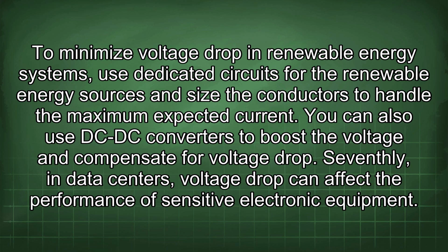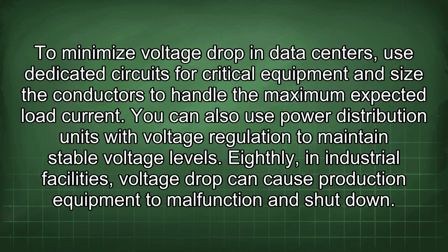Seventhly, in data centers, voltage drop can affect the performance of sensitive electronic equipment. To minimize voltage drop in data centers, use dedicated circuits for critical equipment and size the conductors to handle the maximum expected load current. You can also use power distribution units with voltage regulation to maintain stable voltage levels.